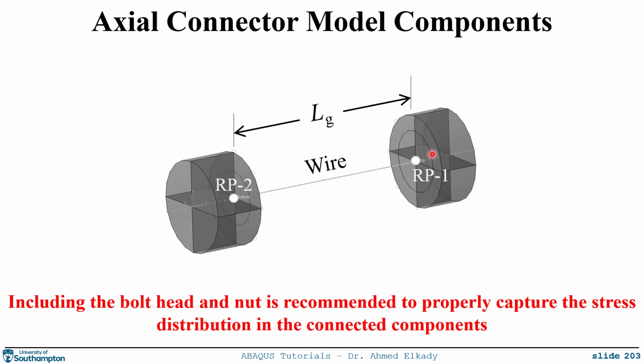Well, the components of your model are as follows. We will be modeling the bolt head and the bolt nut as solid elements. This is not necessary, but it is what we recommend, because including the bolt head and nut means that you will capture the stress distribution properly in the connected components and any yield line pattern.